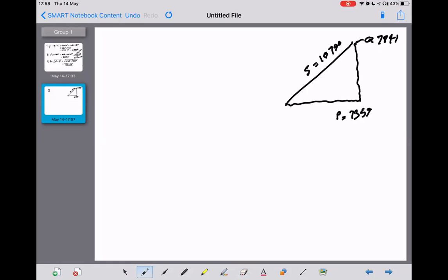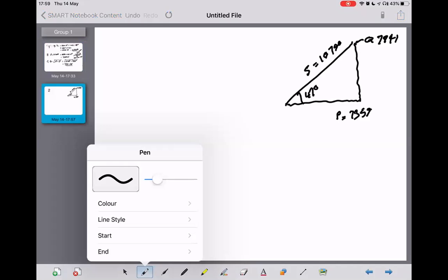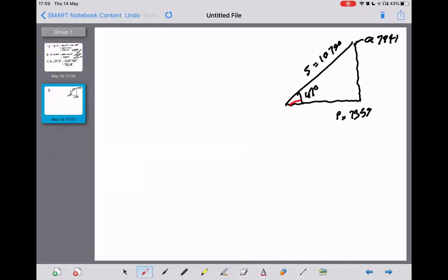How are we going to tackle this issue? It says the new apparent power and phase angle, because this is currently 47 degrees, if a capacitor is fitted that provides reactive power to reduce the overall Q to 1500 VAR. So we're talking about adding a capacitor so that this angle comes down such that Q new equals 1500 VAR.